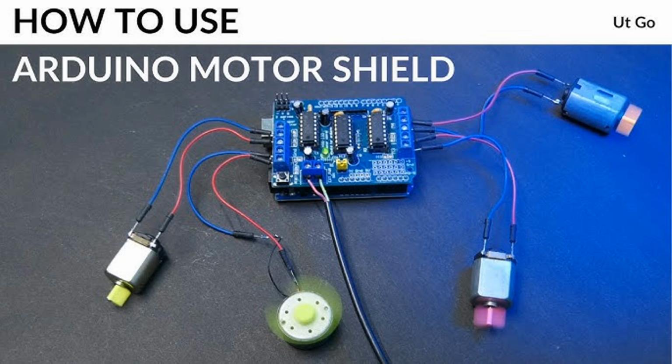Control method. Basic drivers generally require an external controller, such as a microcontroller or a PWM signal generator, to provide the necessary commutation signals. Applications. These are commonly used in applications that don't require sophisticated control, like in simple fan systems, some types of power tools, or hobbyist projects. Examples: L298, DRV8871, TB6612.